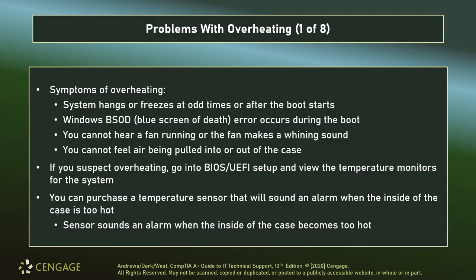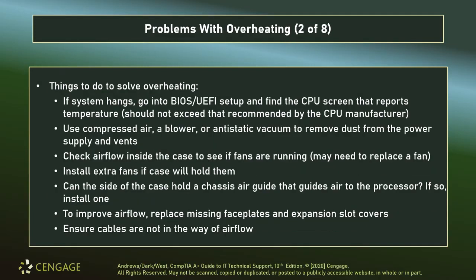If you suspect overheating, of course, you can check the software-based temperature monitors. There are also external sensors that you can buy that you can clip into your case that can trigger an audible or visible alarm. Of course, keeping things clean is probably the easiest way to go about it.